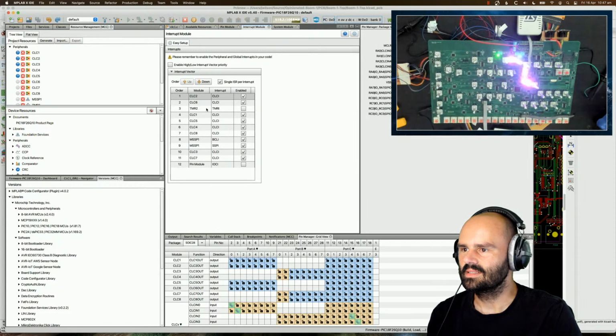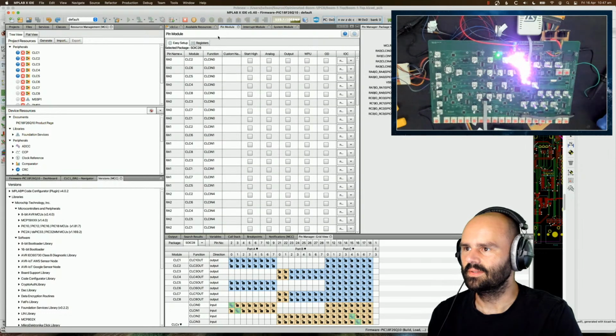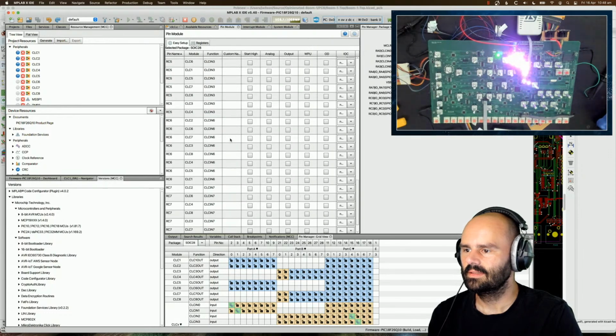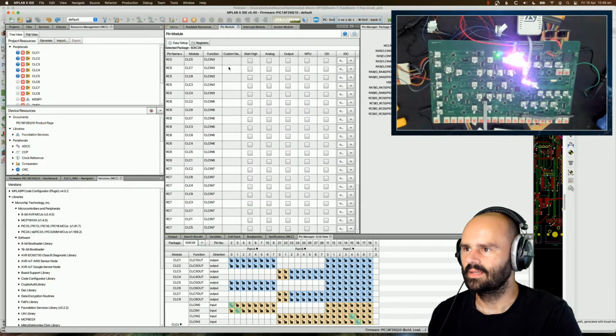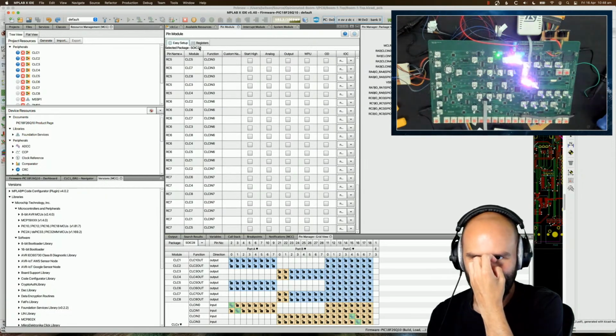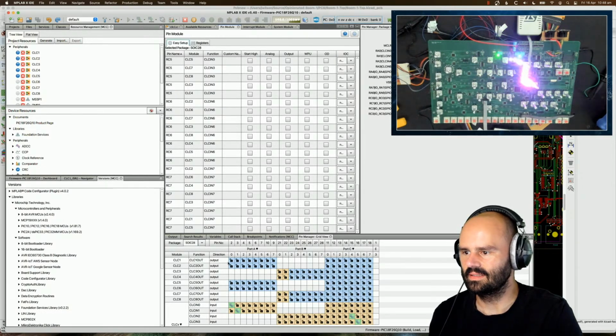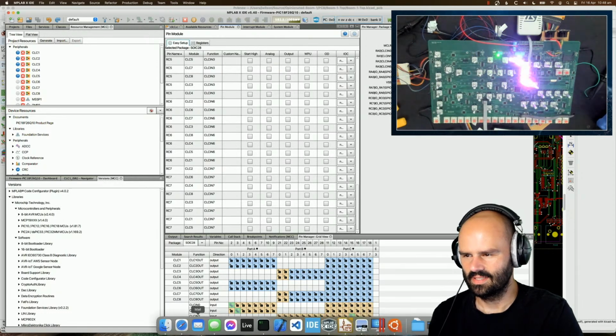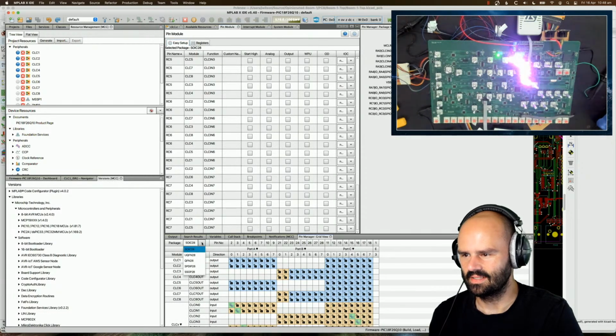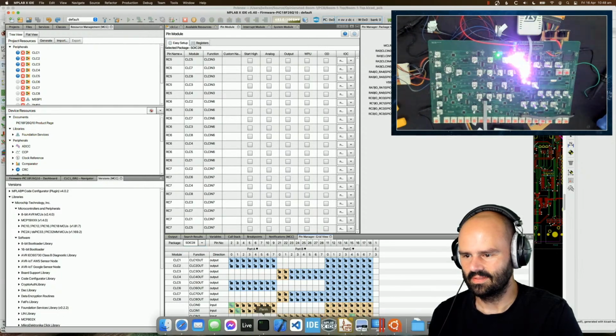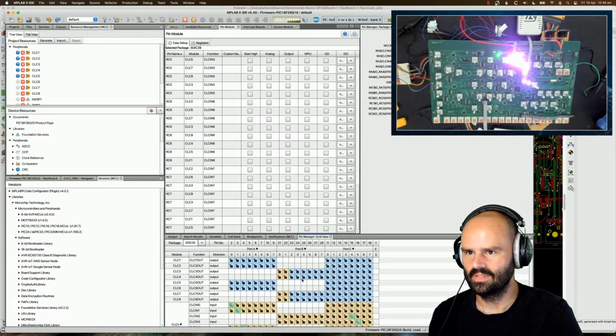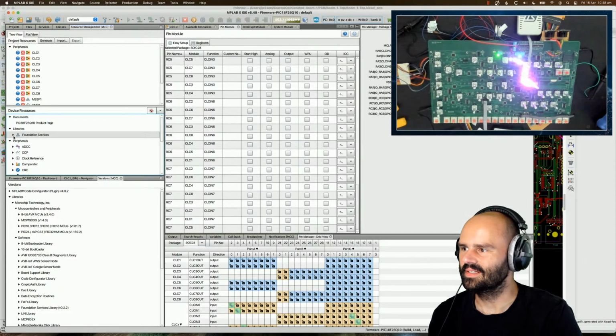What could it be doing, or what could be wrong? So we've got CLCs, all those are enabled in the module. And that all looks fine. And then is the package quite right though? I think we're actually using the SOIC 28. I mean, it's either that or it's the TSOP, but that shouldn't make a difference, because the pin numbers are all the same. Is there anything left to try here?